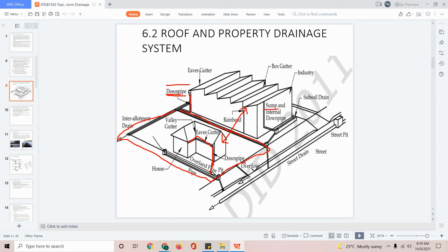We can also have a sump, depending on whether your building is very, very big. A sump is like a mini manhole where there is an intersection of pipes. It is like a small box where you have some intersection in between, and there you put a sump. After that, you go towards the perimeter drainage, and from the perimeter drainage it will go towards the public drainage.